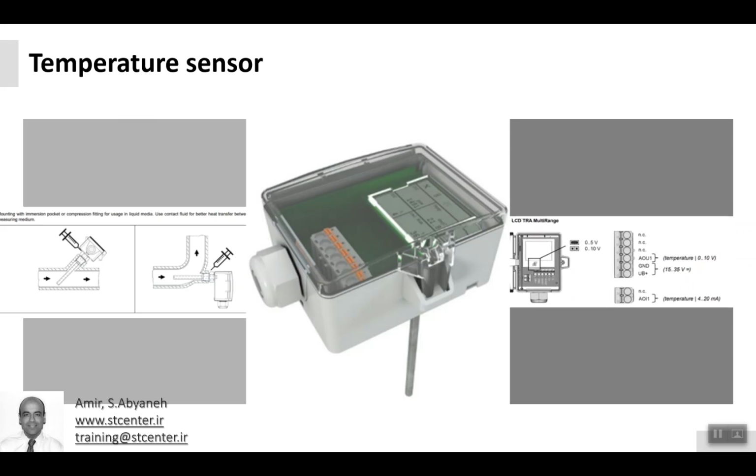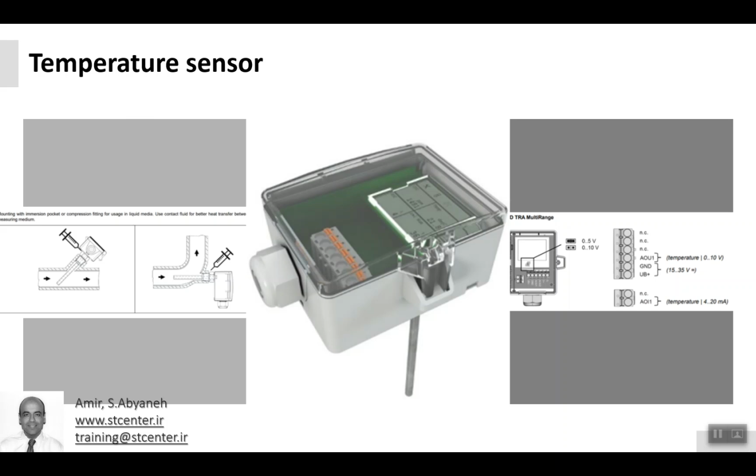Also, it is important about the wiring. Is this temperature sensor a passive resistive type, or is it active and the output is 4 to 20 milliamp or 0 to 10 volt? Do we need to provide an extra power supply and so on? So this is important.